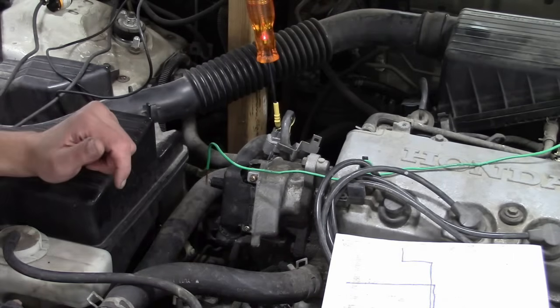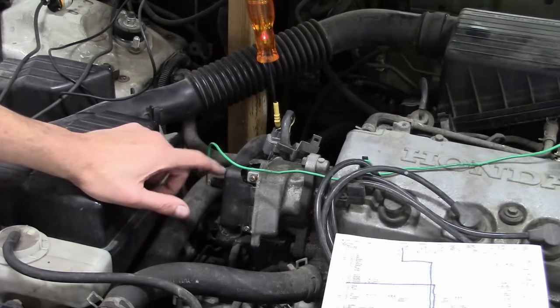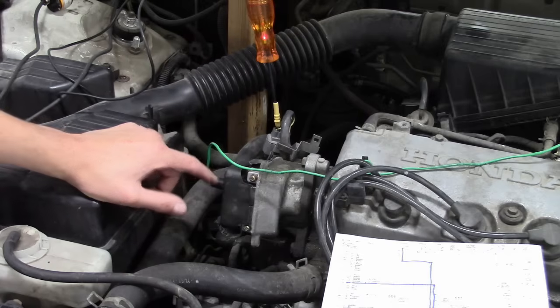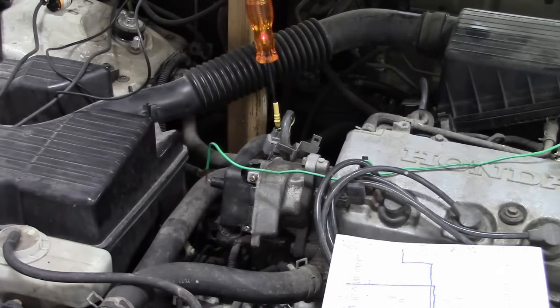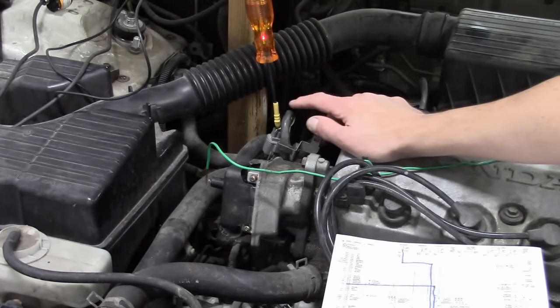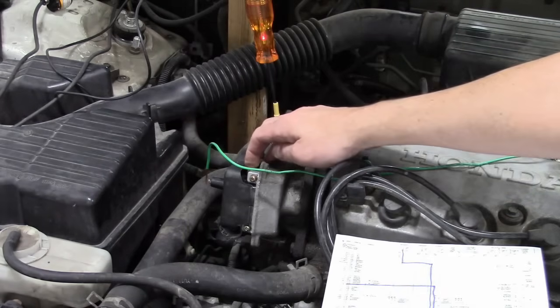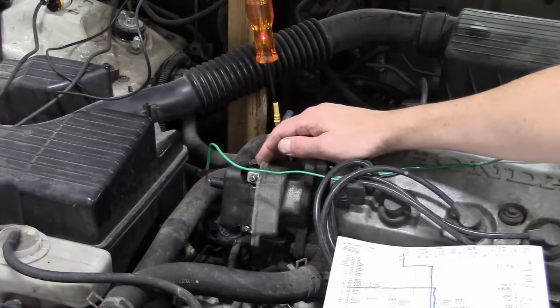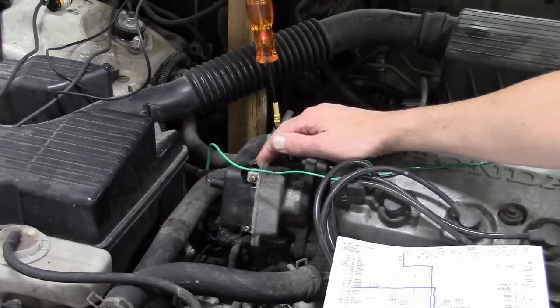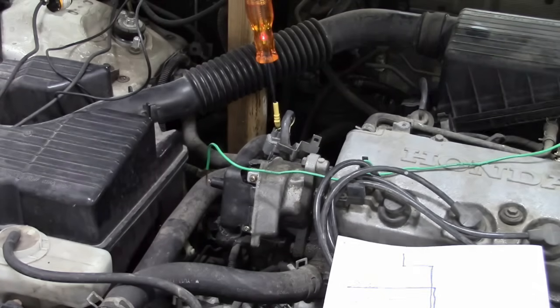This may actually rotate rather rapidly with the one output here, so this could actually flash very fast. To make it easier, I'm going to turn the lights down, and let's see if that flashes as I crank. If it does, that's going to be a pretty clear indication to me that this computer is receiving signals from the CYP, CKP, and TDC sensors, and producing an output. So let's try that.